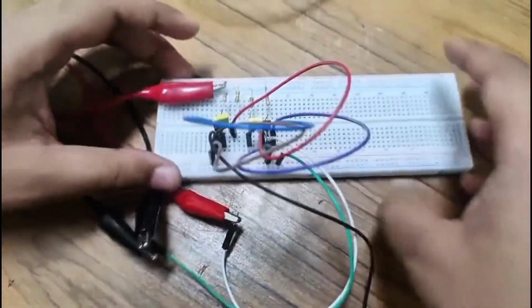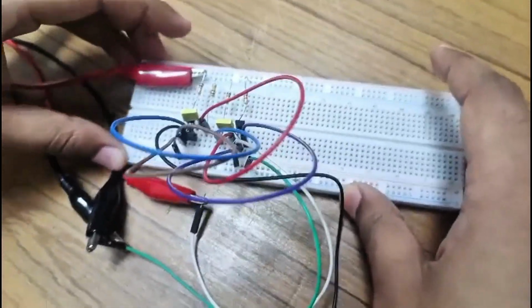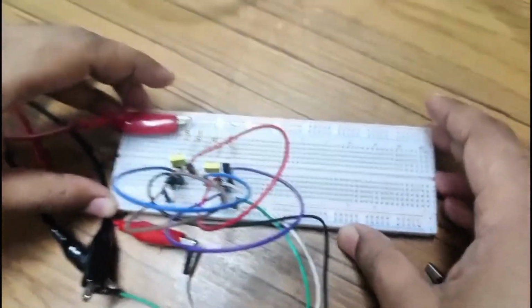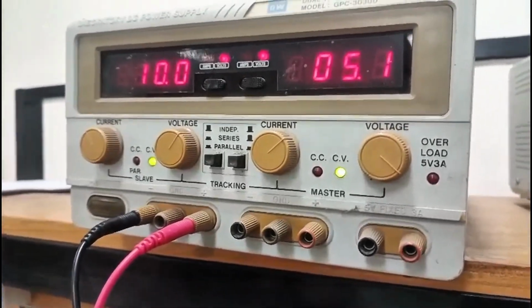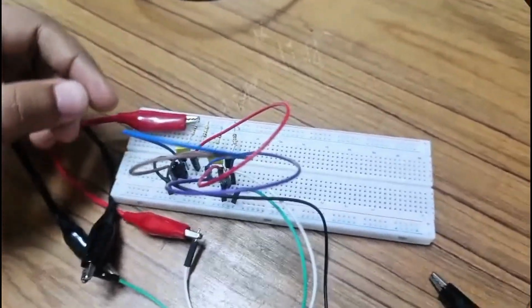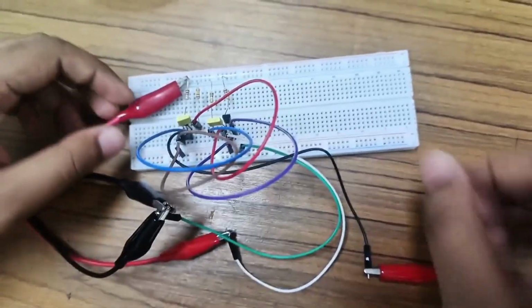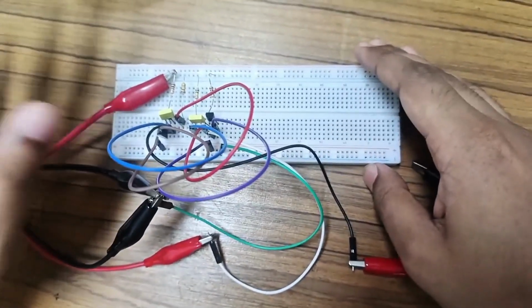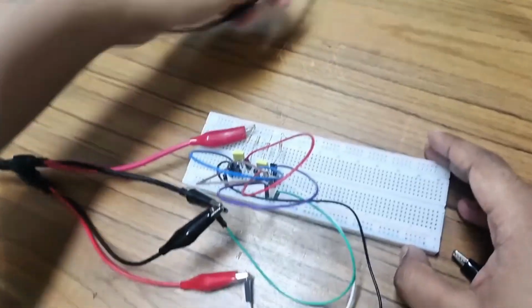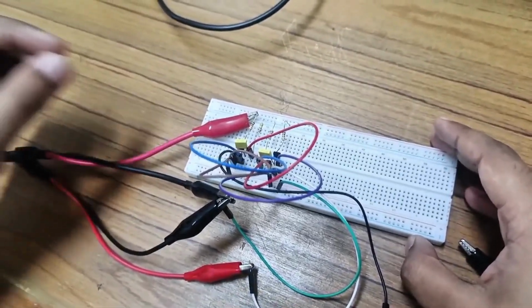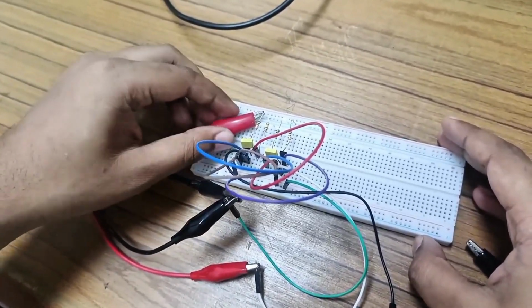We have built our circuit according to our theory. For input we have connected 10 volt DC here, and we are taking our outputs from the collector terminals of both of our BJT transistors. Now to observe the output clearly, we will connect the oscilloscope channels to our circuit step by step. First, we take channel 1 of the oscilloscope. The positive probe of channel 1 is connected to the collector terminal of the first BJT transistor because this is the point where we want to measure the output signal.